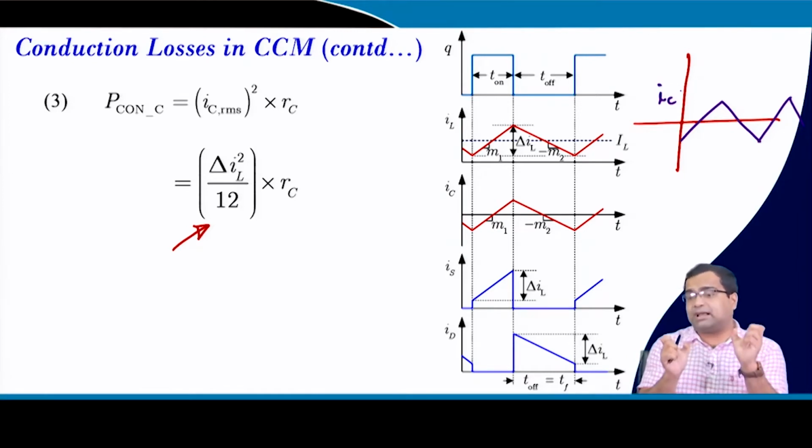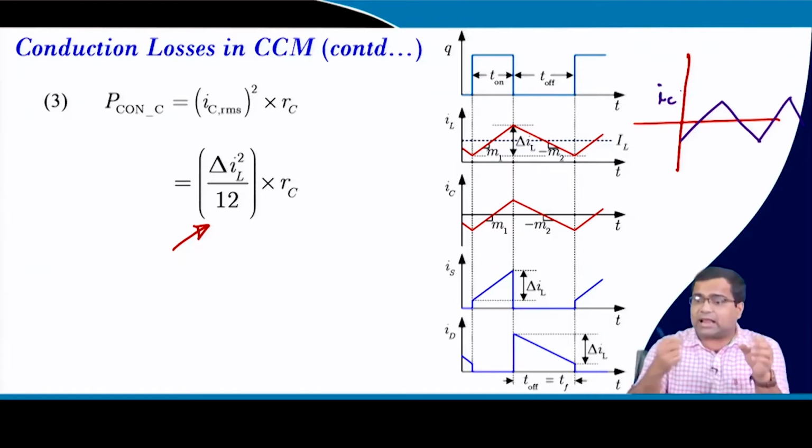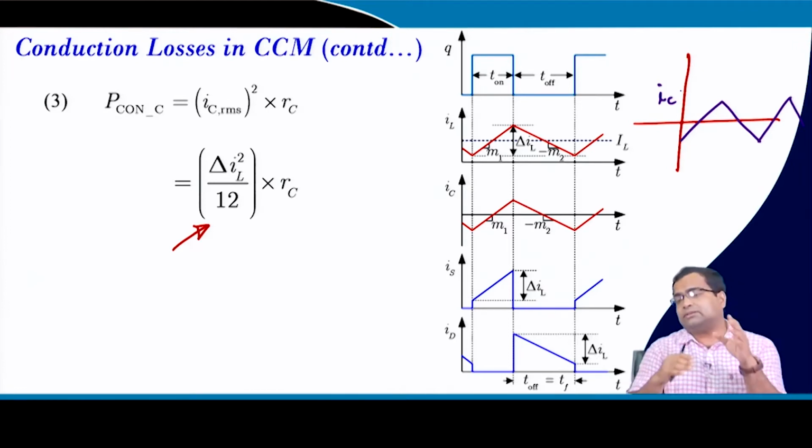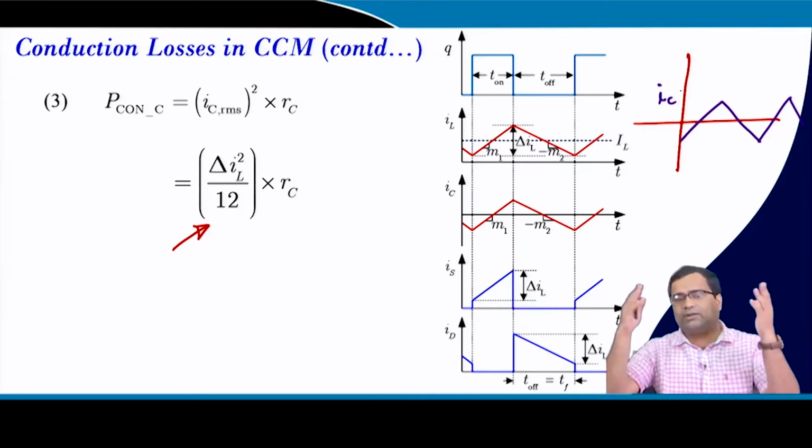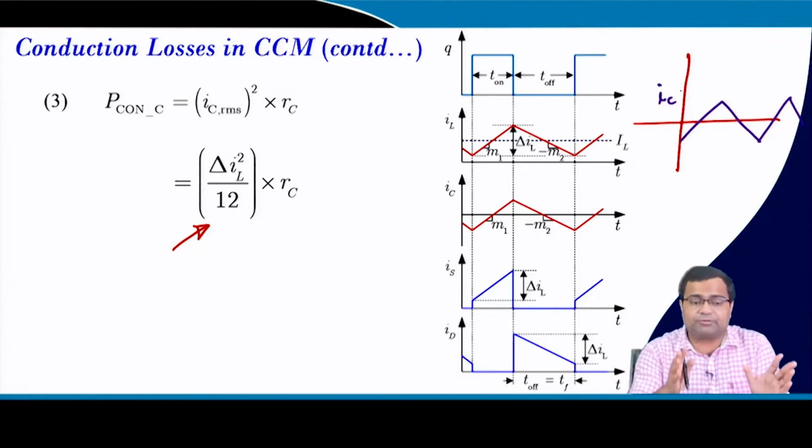But if we take a diode based implementation, this will be problematic, because the diode will not allow negative current, and you have to be very careful about the closed loop control, otherwise your output voltage can drastically increase and go up to the input voltage. So, you have to be very careful.